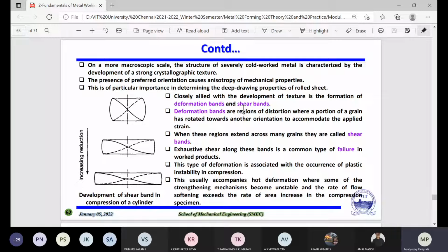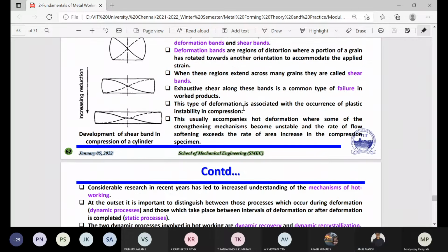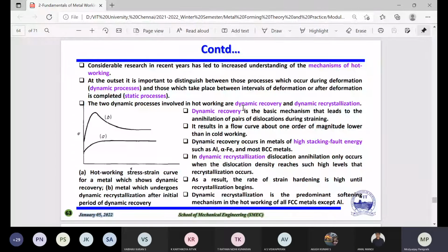You know, when we showed the microstructure in the beginning: recovery, recrystallization, and grain growth. So that means initially you have the grains, then they will stretch somewhere because when you are applying the force, or maybe in the deformation zone, you are creating some new grains there, and those grains again grow and reach the growth stage. Then you cannot grow more, right? Is it clear? Yes, sir.